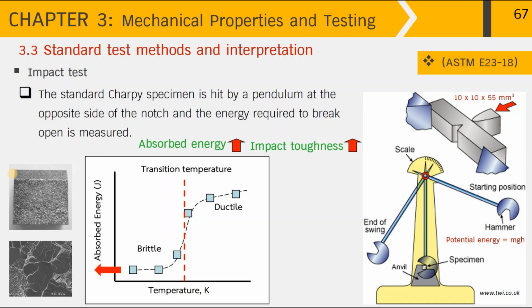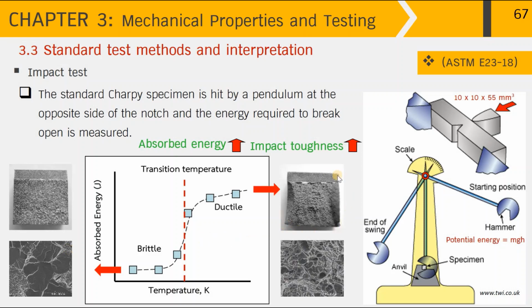That means no plastic deformation is involved in the fracture process. And once we investigate the fracture surface under SEM, we can see a very flat surface over here that signifies very little energy absorbed during fracture. On the other hand, if you're looking at the sample that broke open at high temperature,